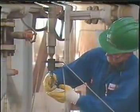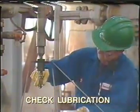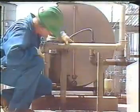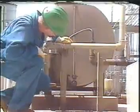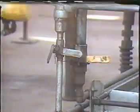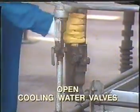Before you start the pump, you should always check to see that lubrication is available to all bearings. In oil-lubricated bearings, check the oil level in the bearing housing reservoir and add the proper type of oil if necessary. For pressure or mist systems, check the level in the reservoir and be sure the mist generator system is operating. If the pump is cooled by water, open the inlet and outlet valves to allow the cooling water to circulate.